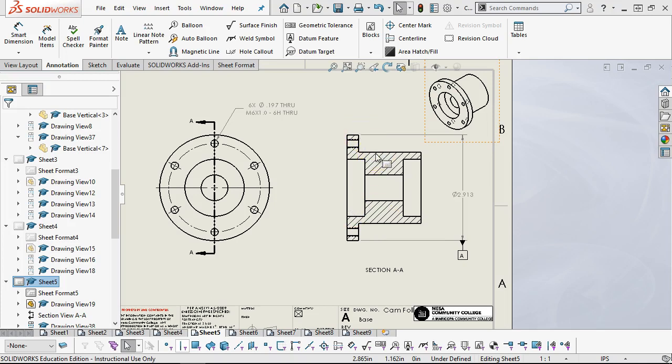All right. So when we looked at this one, really the only critical was the width and position for the through bores, that they line up and stay in sequence. So this might be a good place to pick up the section view. If I do a section view, I don't really need the right view, but I would like to show both of the bores at the same time. So back in the view layout, I'll go to the section view, pick a vertical, go ahead and hit OK, and that can be section B.